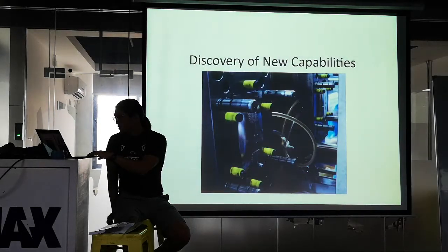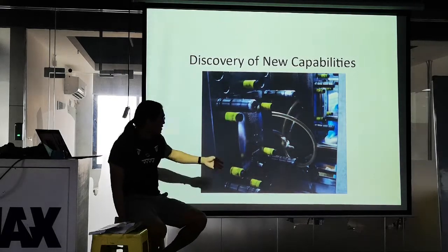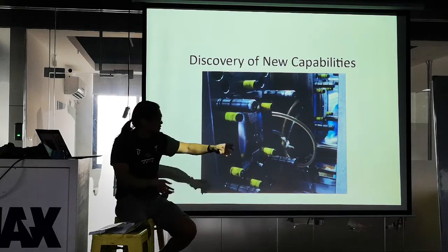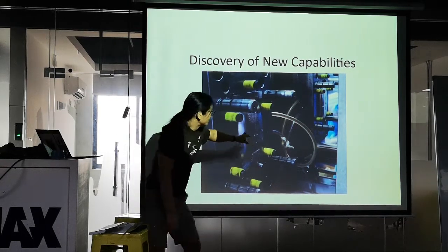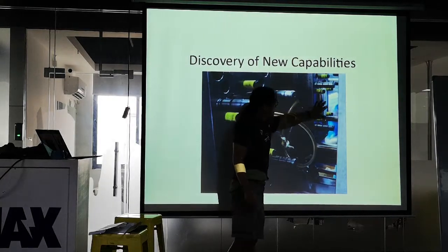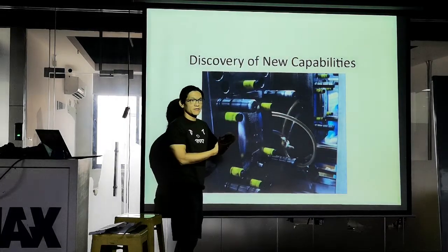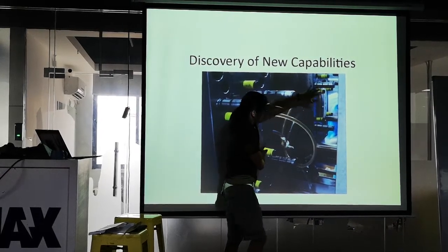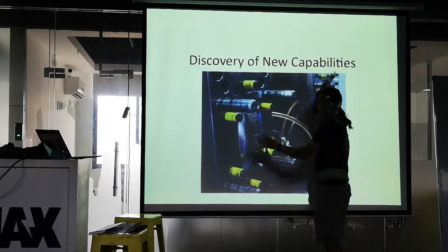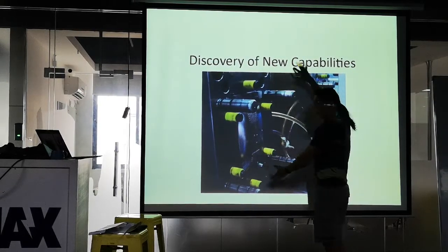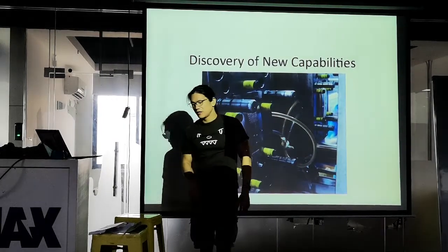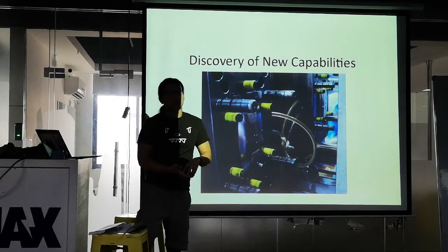So we go to factories to look at molding processes. This one here, we talked about double shot molds, putting two plastics together. This is what a double shot mold looks like. This one here is the hard half. This one here is the soft half. It's the same piece. There are these two tools, and every single time it shoots, they spin around, and then it puts the other plastic on, and it spins back the other way, and then the worker can take the thing out. So it's a really bespoke machine to be able to do this double shot mold.